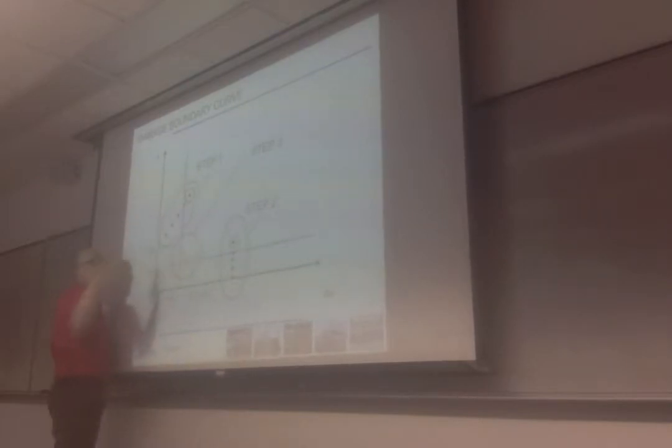Some other people, ASTM suggests that it's going to be somewhere between those two, to use an average value. So it depends, yes. Did you say that the damage occurs on the boundary? So even when you're on the boundary line, damage isn't occurring yet? That's the way that some procedures dictate you to do it. So that's the conservative approach because you have little increases in drop height.